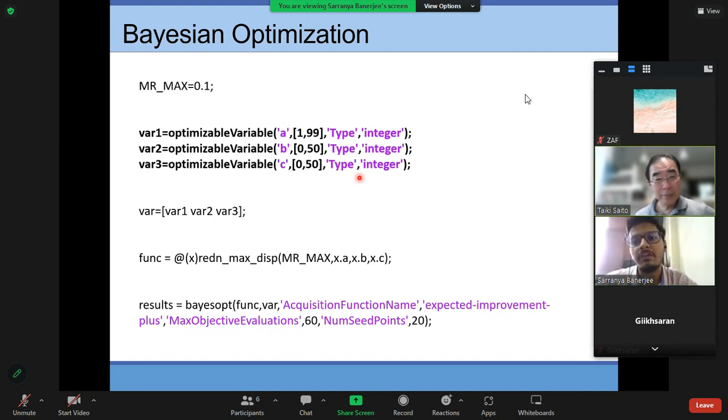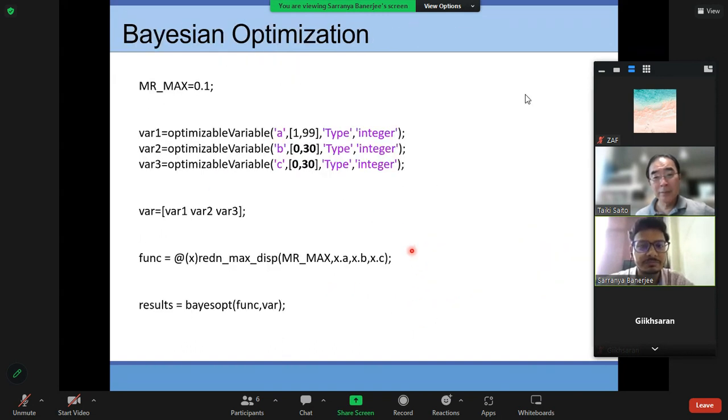Obviously, we do not have it for the hybrid systems, but for normal damped single degree of freedom or multi-degree of freedom systems, we have some papers, say Warburton from 1982. From there, I saw the different damping ratio values, and I found that until 2% mass ratio of the TMD, the maximum damping ratio is around 30%. So I just capped the maximum damping ratio to 30%.